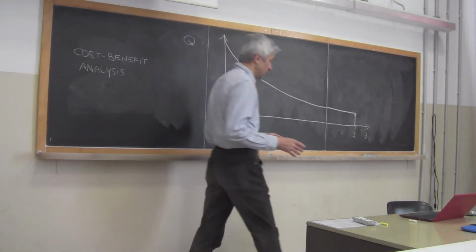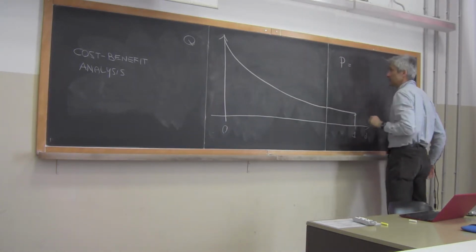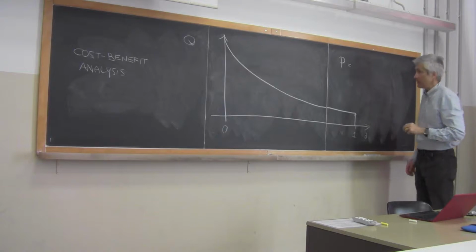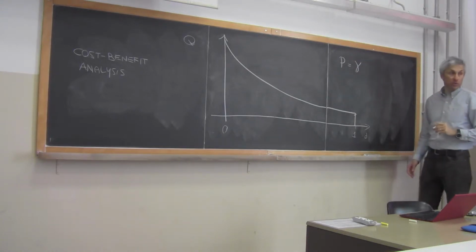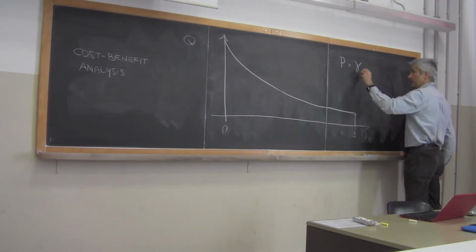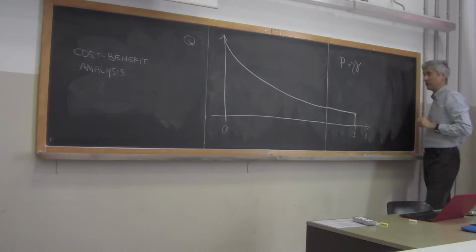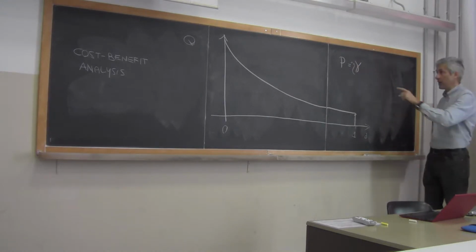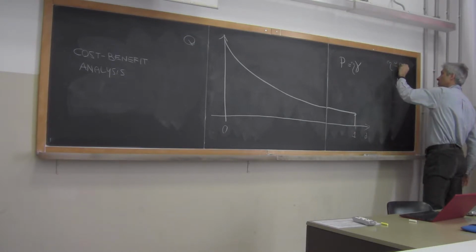Remember the hydropower: if you indicate the power that you get from a plant with P, the power is proportional to the specific weight of water, okay? This is fixed. And then there is a coefficient of efficiency, which at the max is about 0.7.